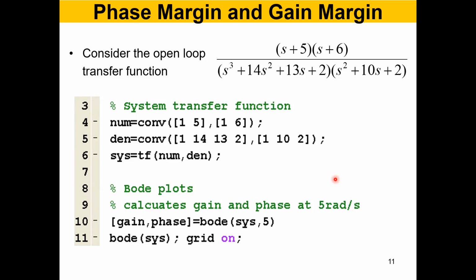If we send different frequencies to this block, what is coming out? Whether you get attenuated signal, amplified signal, phase delayed signal, phase lead signal, whatever, right? And we basically want to know the magnitude versus frequency and the phase versus frequency.